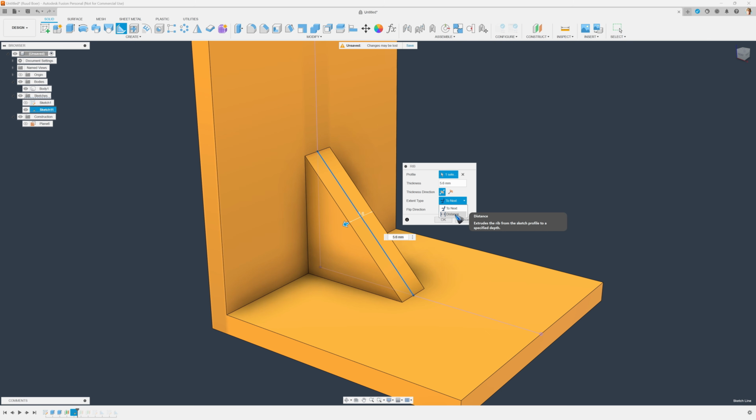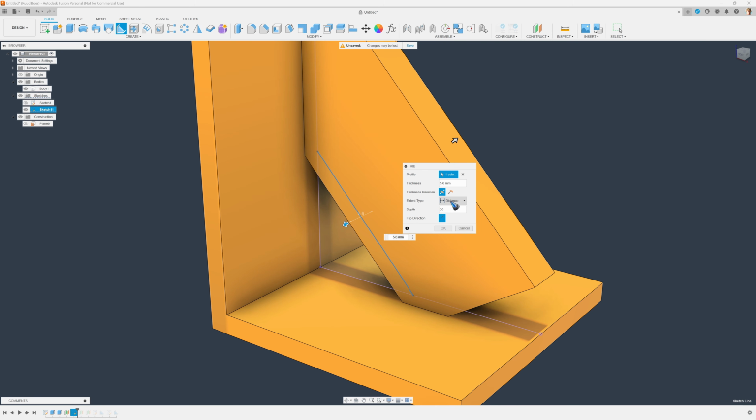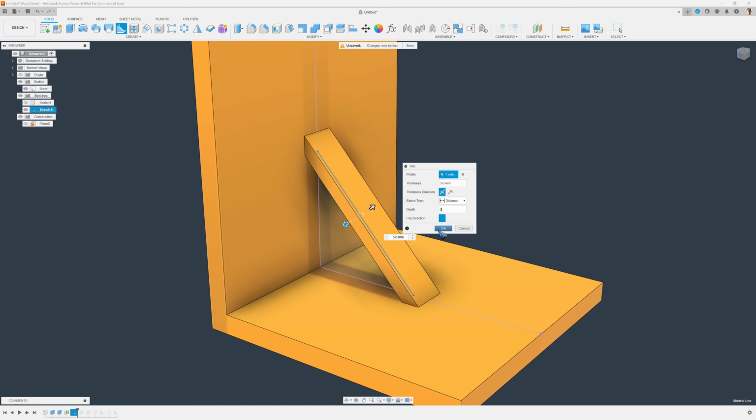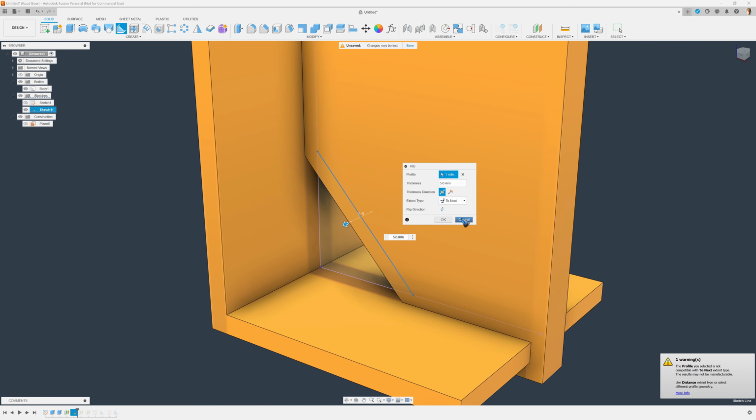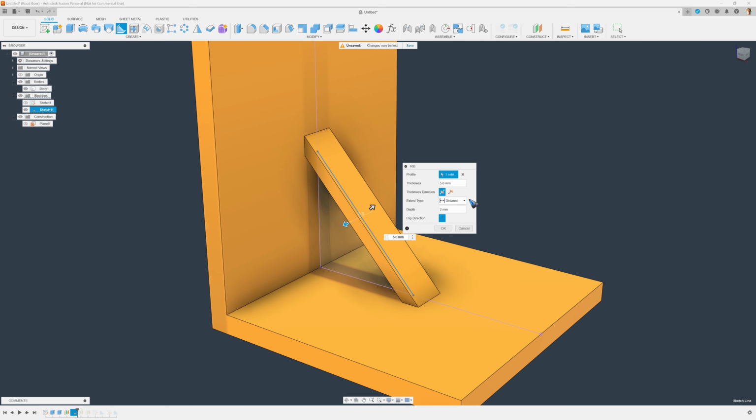We can also change that to distance, and that means that we can give it a thickness, and it now becomes not a complete filled rib, but it becomes, oh, that was a bit too much, it becomes more like a bar like this. In some cases the rib does crazy things. Some cases you end up with a rib like this, and that means only that it tried to find the two nearest faces, but we have to flip the direction. So in most cases the whole thing will be solvable.